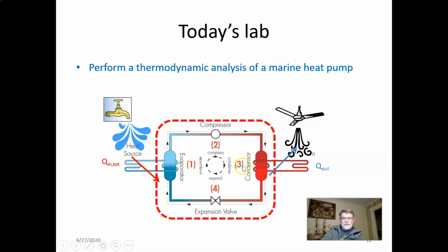So, recognize the typical refrigeration cycle here. You compress with the compressor, then you condense. For a refrigerator, heat is not used, it's just removed at the back of a fridge at home. You can feel it, it's hot, but it's air cooled, hence the need to keep some space, make it breathe and eliminate the heat in the back.